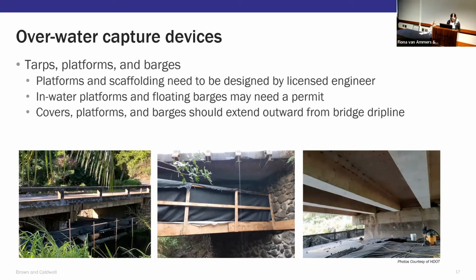water. Platforms and scaffolds should always be designed by a licensed structural engineer, they would take into account the loads from the platform itself, any people or equipment that are standing on the platform, and the weight of the debris that's expected to fall from the bridge onto the platform.